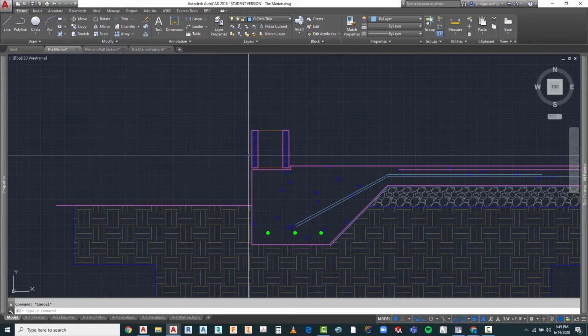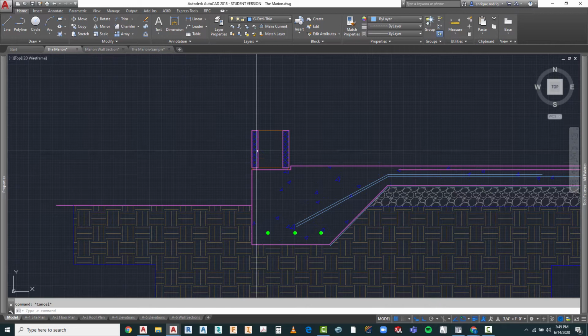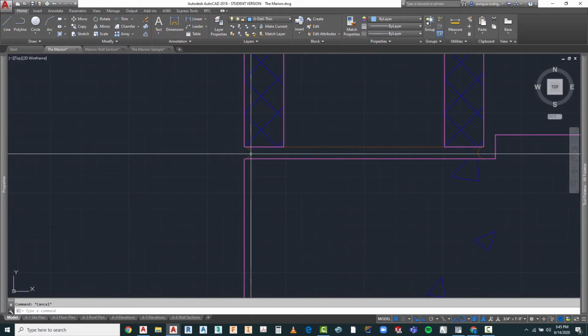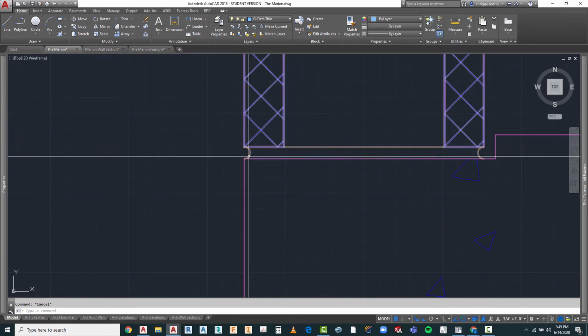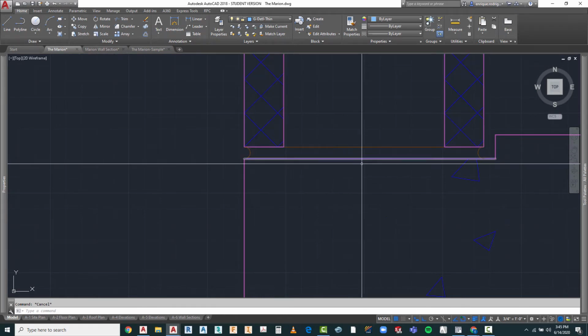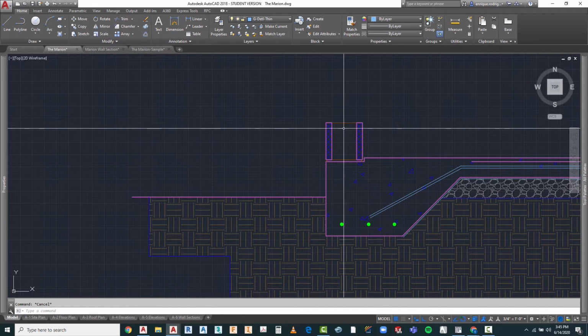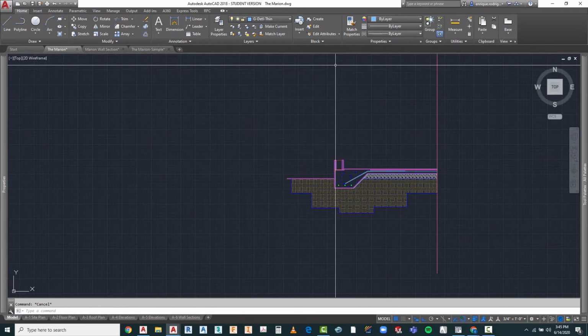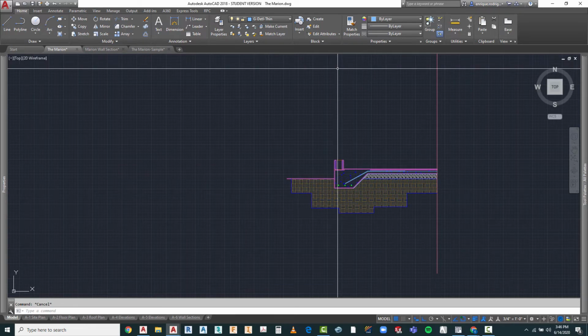Now think of this as the first course that your masons would start building around your house. This represents your mortar that you're going to be using, and then we're going to repeat these until we reach the desired height before we do a tie beam across the top.